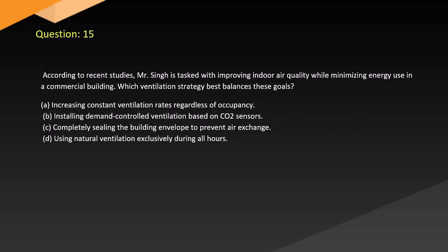Question 15. According to recent studies, Mr. Stassing is tasked with improving indoor air quality while minimizing energy use in a commercial building. Which ventilation strategy best balances these goals? A. Increasing constant ventilation rates regardless of occupancy. B. Installing demand-controlled ventilation based on CO2 sensors. C. Completely sealing the building envelope to prevent air exchange. D. Using natural ventilation exclusively during all hours.